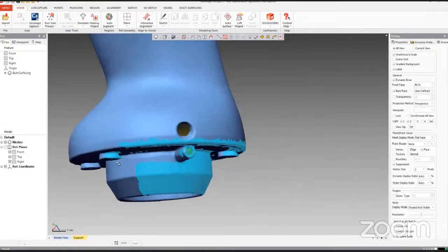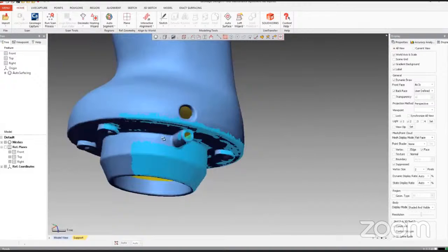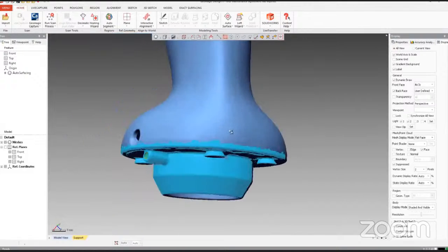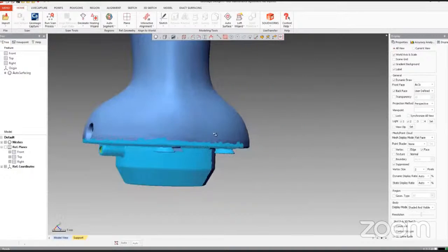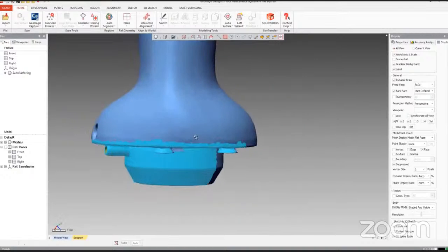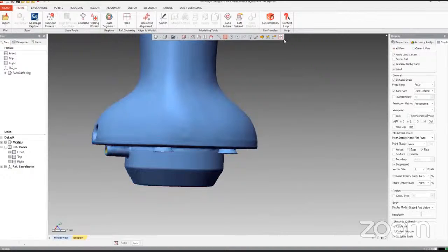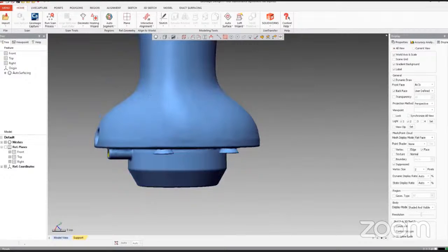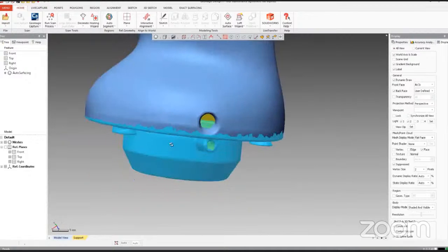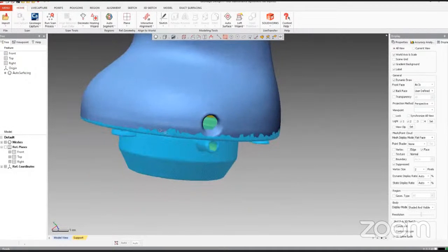So since we want to select the whole region at the bottom, we will uncheck the visible only option and reselect that bottom region. By unchecking it, we are able to get the selection, and we can just select the line and press the control button with the visible only checked.